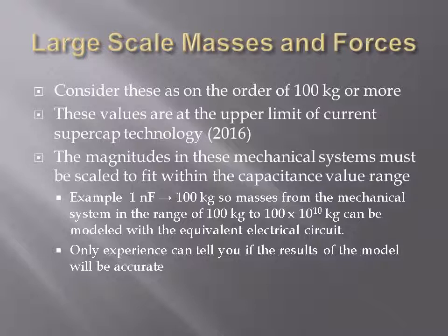However, we can continue because the magnitudes in these mechanical systems can be scaled to fit within the capacitance value range that we can find easily. So let's take as an example setting a basis of 1 nanofarad being mapped to 100 kilograms.